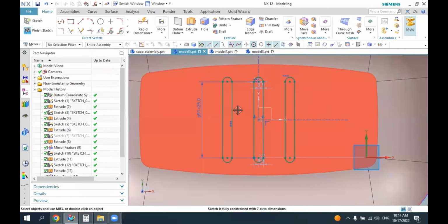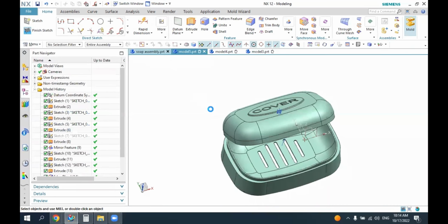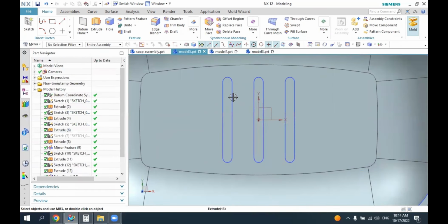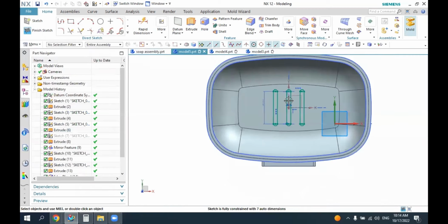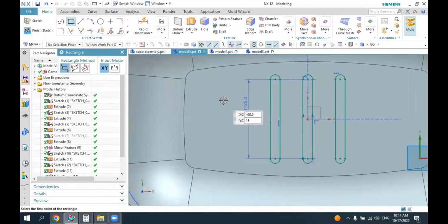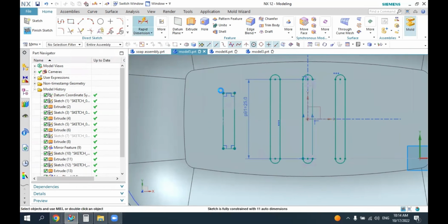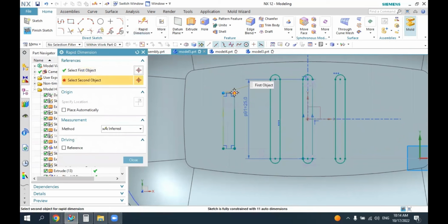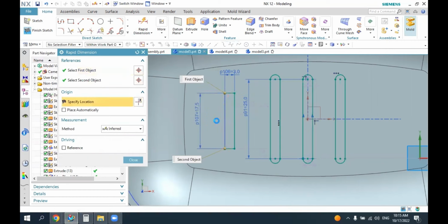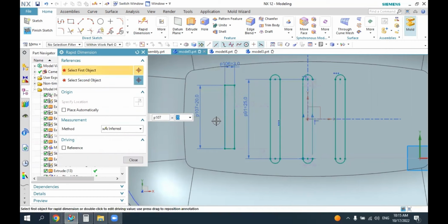So we created this sketch, and we can create the same here, but the length is a little bit smaller. So firstly, just double click on it and enter the sketch, and let's create a rectangle again, the smaller rectangle, and with the same distance here of 3 millimeters, and let's make this one 20 millimeters smaller than the other one.